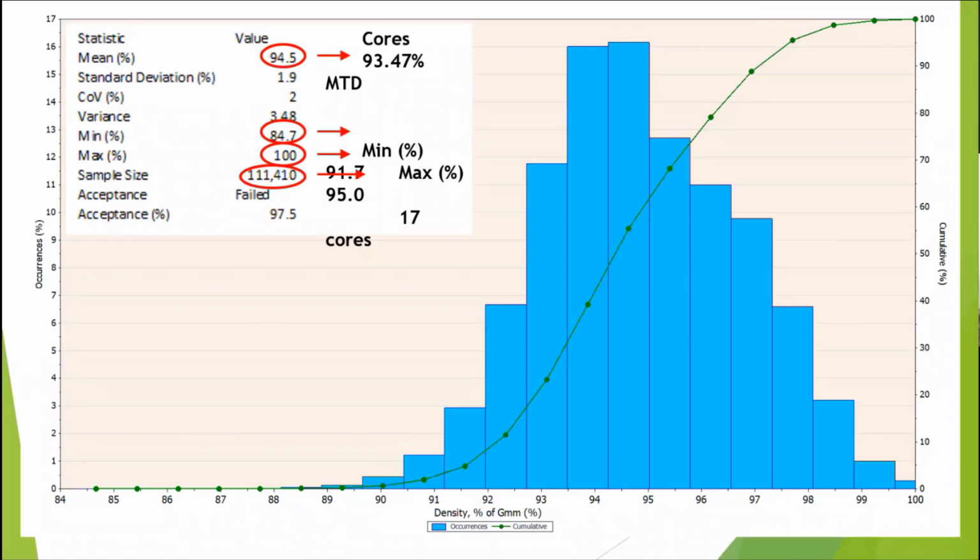The other thing is, and I had a lot of discussions with John and others, we typically fog seal the mat as soon as we finish it, right? Before we move traffic control. And so that affects the numbers. Well, yes, it does, because one of the ideas of fog sealing it is it closes up those surface voids, which means what? Your air voids go down, density goes up, because that's less space for water, moisture, air to get into.